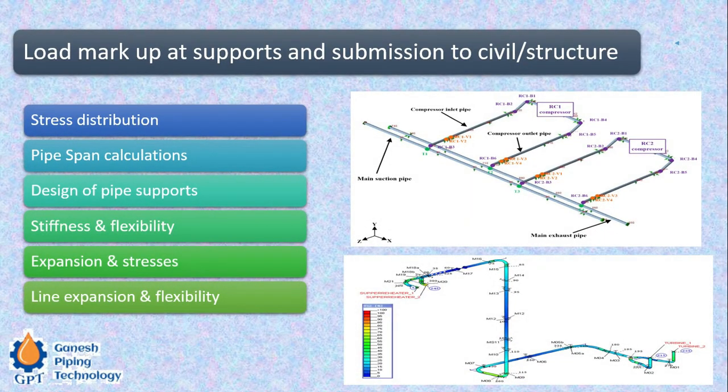Then final is the load markup at support and submission to civil structure. We have seen that wherever there is a support location, we have considered it as a node, and there will be a chart wherein we have to mark up the loads that are coming at these supports, which we are calling nodes, and this is marked up on the structural layout, and this has to be submitted to the civil and structural team. So they will come to know the position of the supports, what load is coming on those supports, and they will design the structure which is capable of withstanding those loads which we are providing. We means the stress team is providing to the civil structural team.